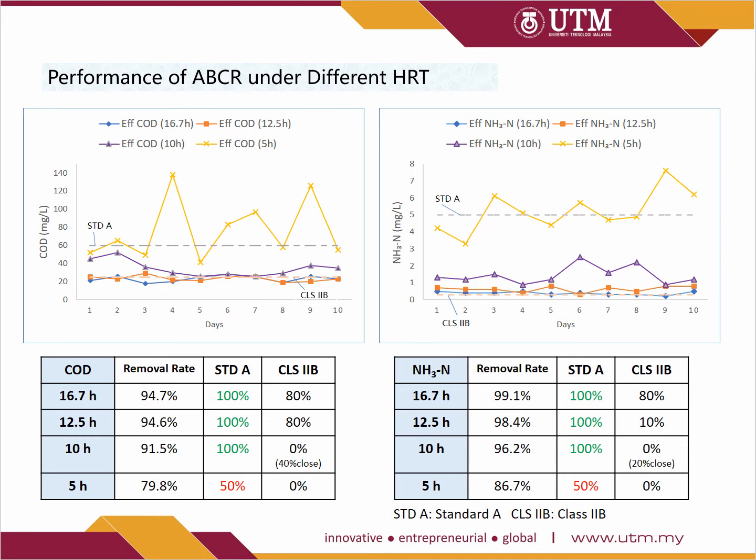If we use the novel ABCR using the MBS media, we can see that at more than 10 hours retention time, hydraulic retention time, which means how long the sewage water is kept within the reactor, the holding time needed is about 10 hours for all the pollutants to achieve below the standard.